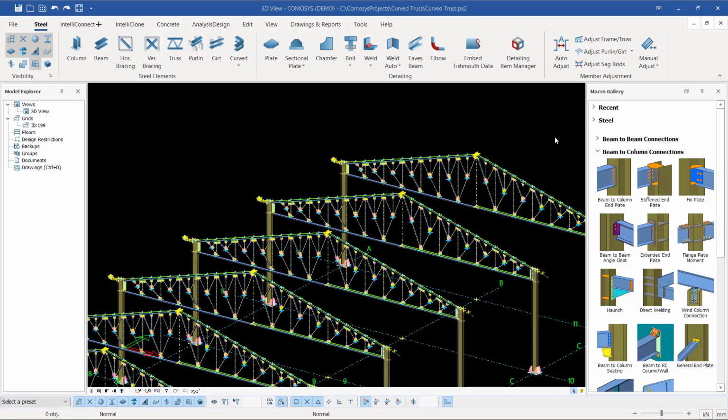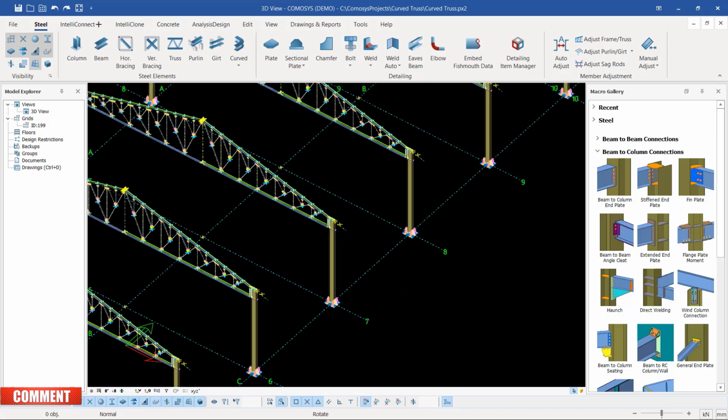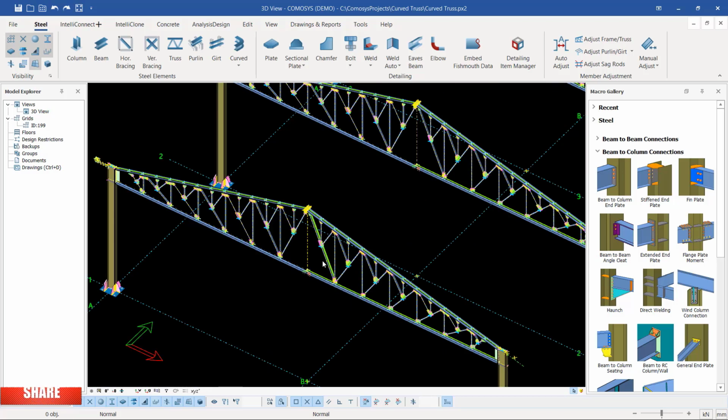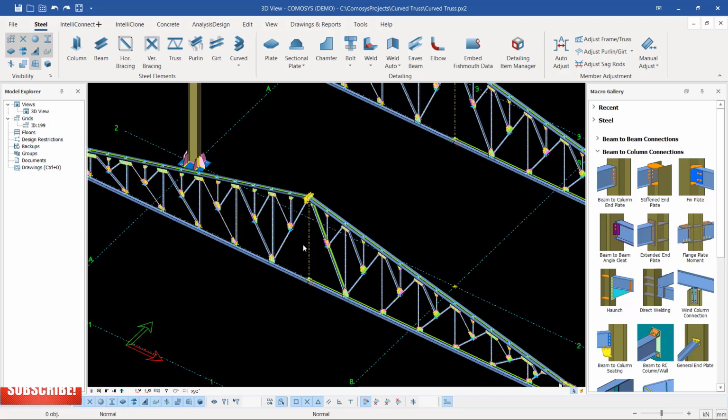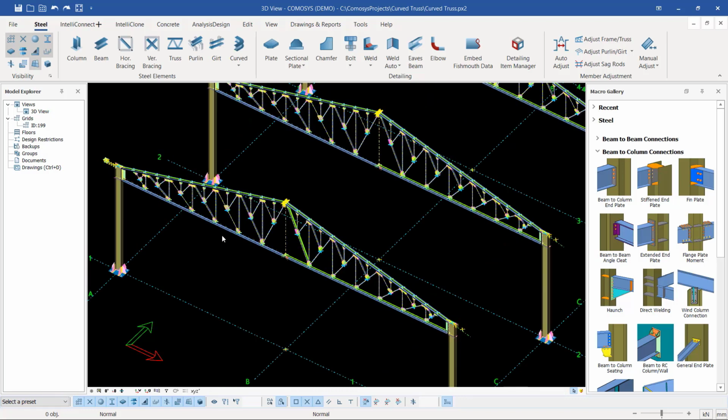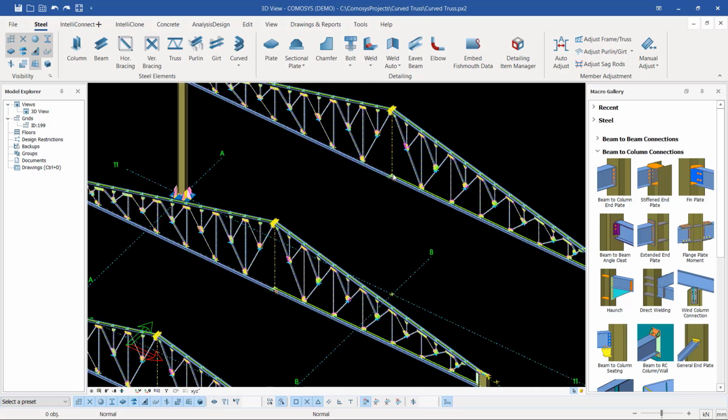Welcome back, and we're moving to another part of this particular model, and this is part 8 of how we can create a truss. So we want to modify something here. You see, at the gable end here, at both gables, we have the truss, but you'll find it very hard to clad this end of the truss because we will not have a column beneath this bottom chord. Same applies to that end, and probably you want to have your doors on this far end, and if maybe you don't have a door there, you maybe want to clad, maybe using iron sheet or maybe just masonry wall, and it will be hard if we don't have a column here.